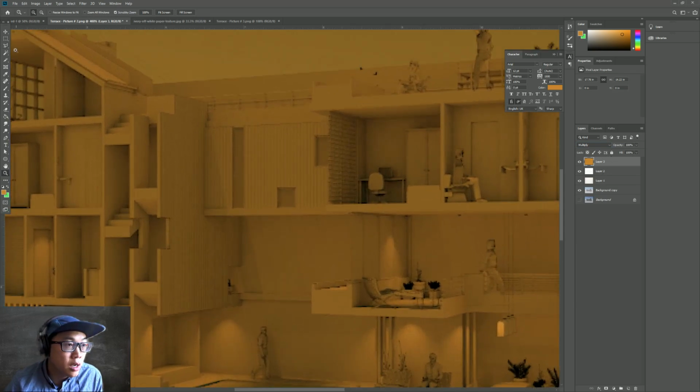And how I do that, I'm just gonna use this polygon lasso, press the point, and to keep things straight, I press shift, so it's gonna be stuck to one axis, and click on the points. Shift, and of course when it's a bit at an angle, you just release shift, so you just go all around.